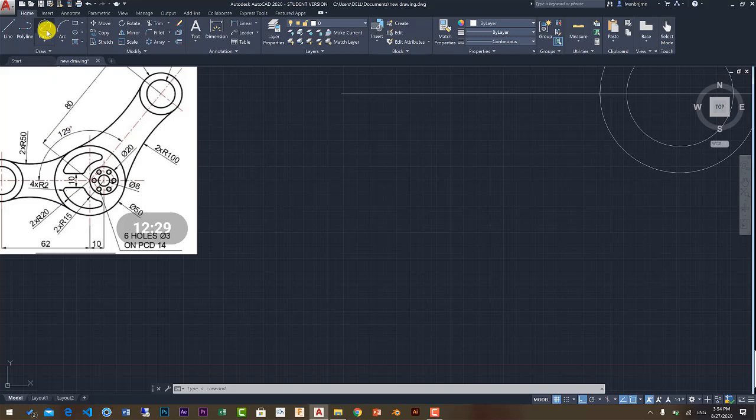So I'm going to use my circle tool. You can use the arc tool as well. Let's use my circle tool. Specify radius of 20, and then the next one will be 15. Then I'll add my fillets of 2 units.